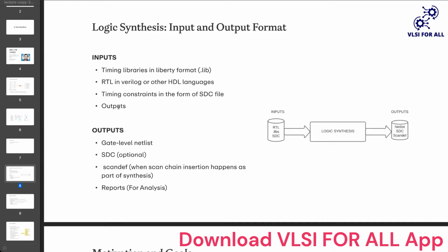Sorry, this is a typo, but going to the outputs, like I said, we have the gate level netlist that is generated. Though you give the constraints as an input, you also write the constraints as an output. The reason being, this design after logical synthesis is taken into physical implementation, also called PNR.